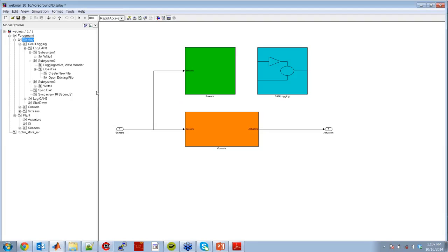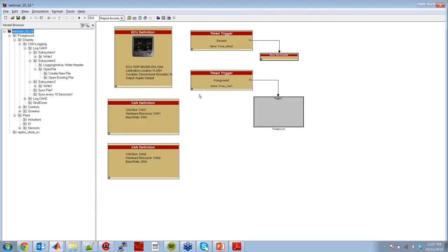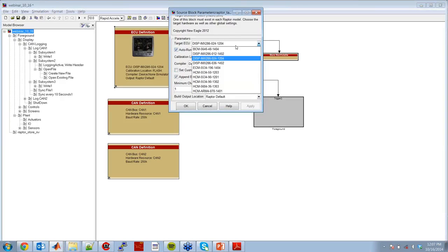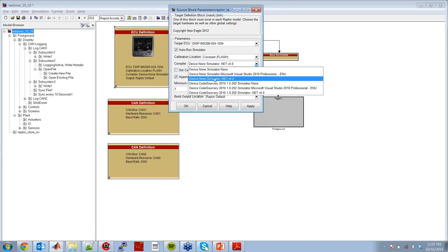You might talk about the target definition and configuring the compilers for simulator and in the embedded. Yep. So we have 3 targets that we can target for the displays. We have our vCAN Lite, our vCAN, and then our vCAN 800. So sorry, vCAN 320 Lite, vCAN 320, and vCAN 800. We're going to build for the normal vCAN 320. And you have the option to build for the simulator, which is the PC simulator tool we saw earlier, or the target hardware. Code Sorcery is our compiler. So we'll do both the Code Sorcery and the simulator.